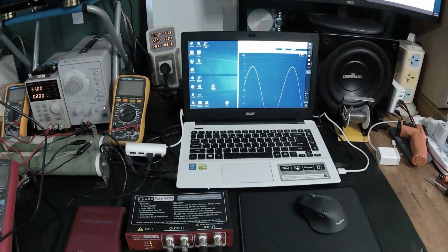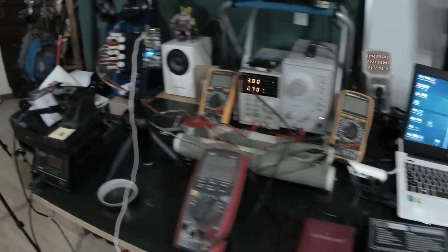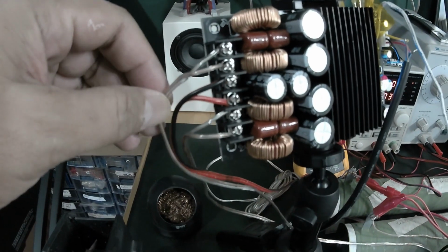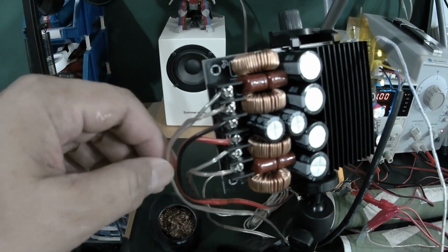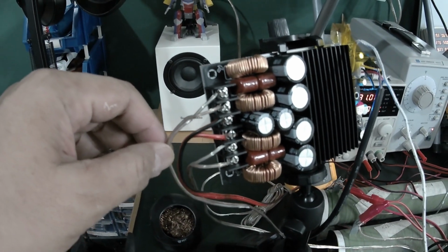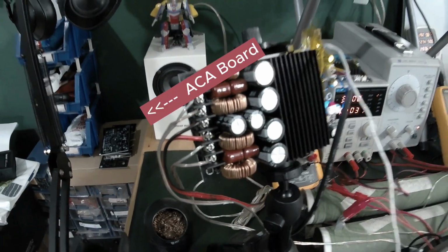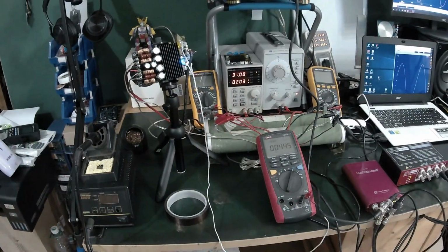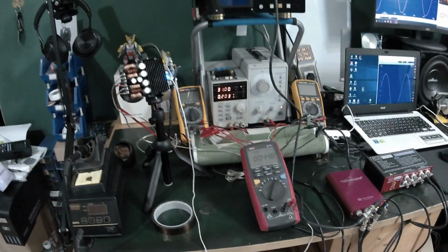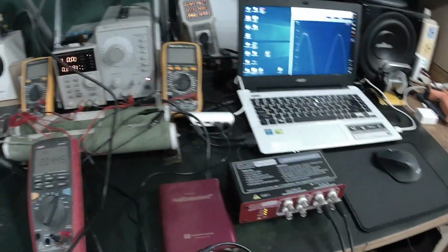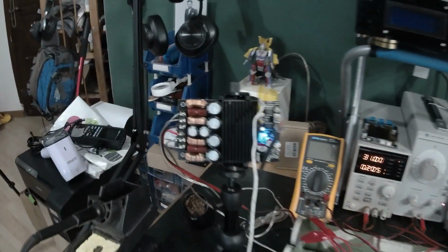The main reason I bring up the grounding again is that the speaker terminals in here are in a BTL mode, called bridge-tied load, where none of them are referred to the ground. If you make use of grounded equipment, then this amplifier may not work.